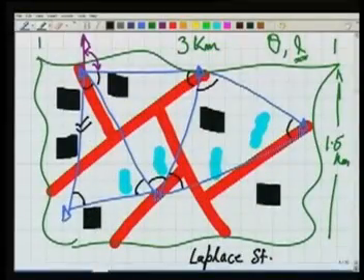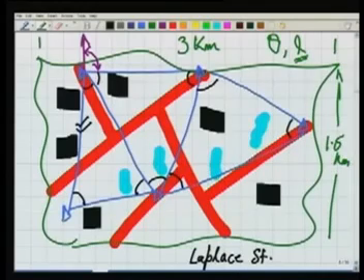Similarly, starting from the known line, our known line here is this, and with all the measured angles, we are finding the length of all these lines. In order to exercise a check, because in our very first lecture we talked about the significance of check in surveying, I can also measure one more length here in the field.